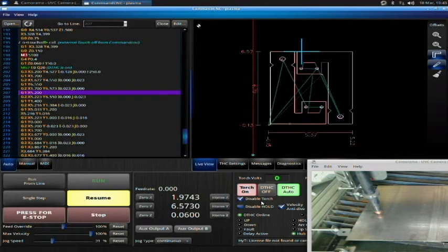You will not be able to just hit resume and have it run, okay? Because the arc will not automatically refire and restart the cut, okay? So it's very important that you do not pause the table during a cut. Now, I can rewind it and fix the issue, and we'll discuss that in later videos on how to take care of that.